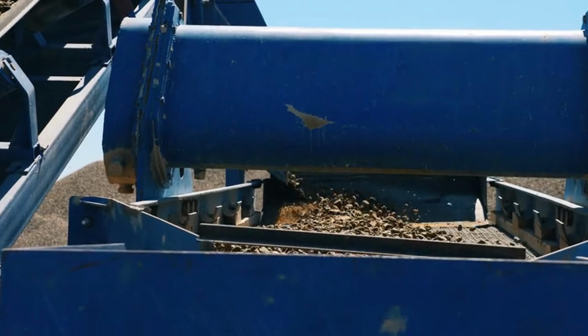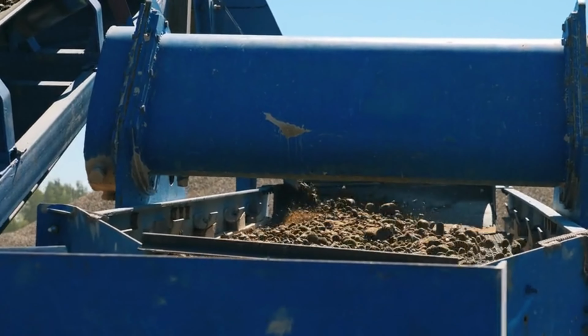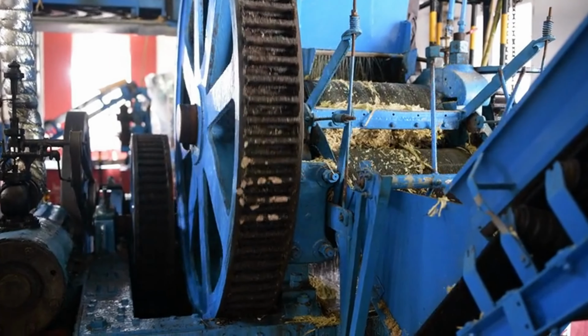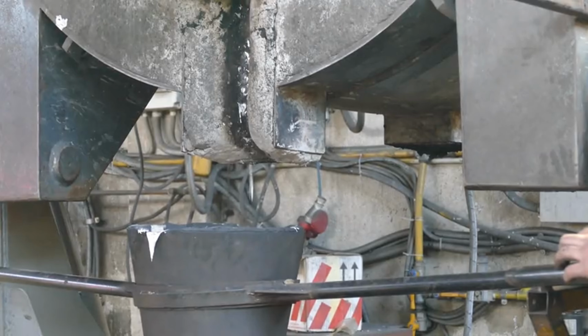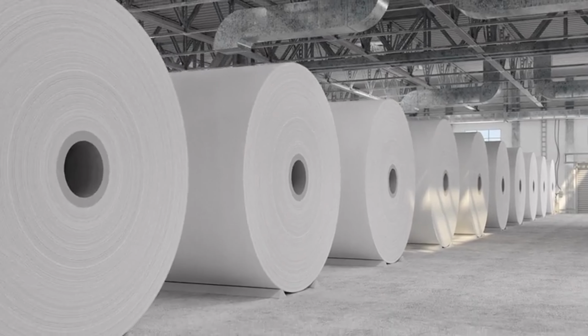2. Pulping. The wood chips or recycled fiber are turned into pulp, using two main methods. Mechanical pulping uses grinding and refining to break down wood fibers. Chemical pulping uses chemicals, for example, sulfate or sulfite process, to dissolve lignin, separating cellulose fibers. 3. Pulp cleaning and refining. The pulp is screened to remove large debris. It is refined to improve fiber bonding, which enhances paper strength.